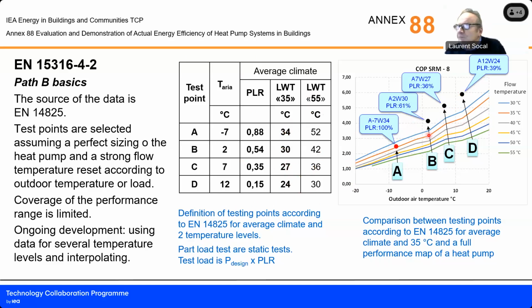And this is a question about the compromise between the number of data and the accuracy and exhaustivity. I mean, by exhaustive, covering all the possible and, of course, likely operating conditions. But think about just using this heat pump on, for example, a fan coil. You would use a constant flow temperature, not, of course, a decreasing leaving water temperature.